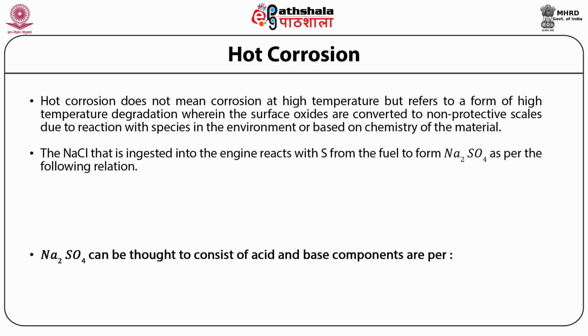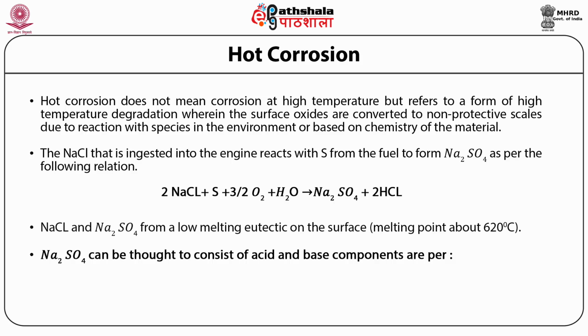The NaCl that is ingested into the engine reacts with sulfur from the fuel to form Na2SO4 as per the following reaction: 2NaCl plus S plus 3/2 O2 plus H2O gives Na2SO4 plus 2HCl. NaCl and Na2SO4 form a low melting eutectic on the surface. The melting point is about 620 degrees Celsius.